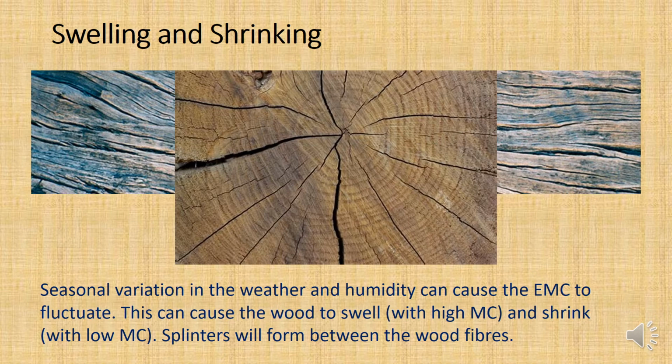Now, when you have high moisture content, low moisture content, it's going to actually split those wood fibers. And so when you're looking at lumber from one end, basically the cracks that emerge, they are radial. They go from the outside to the middle, and they all conjoin at what is the pith. So when you have big cracks like that, you're drastically reducing the strength of the wood. Drastically. You're probably reducing the strength by 90+%.